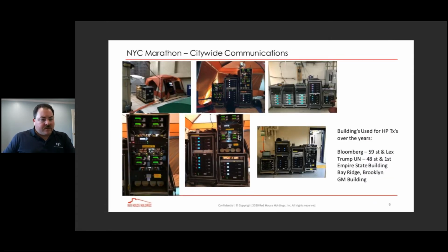So these are just some pictures that we had of some of the rooftops when we did more traditional comms. You can see the large amplifiers in there, in the silver, and then the regular repeaters. We'd have to run these to get 20 watts per channel to cover citywide radios. Those amplifiers have to be a few hundred watts, requiring a significant amount of power. And then after that, a significant amount of LMR and cabling to get up to a lot of these rooftops.